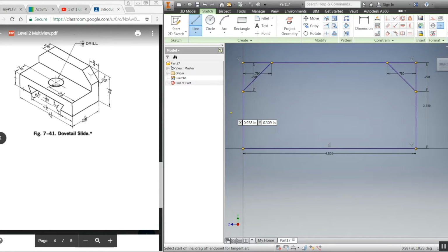I'm then going to go ahead and look on the bottom here. So we come in 1 inch, then I have 2.5, so I'm just going to make those two lines. I'm going to go in 1 inch, and then I'm going to go 2.5. And that's going to set me up for my basic shape. Now it also says a 1/2 inch up, and there's another line that goes across. So what I'm going to do is make two angled lines here with a line across in between them. I'm going to try to make sure they don't lock onto anything.